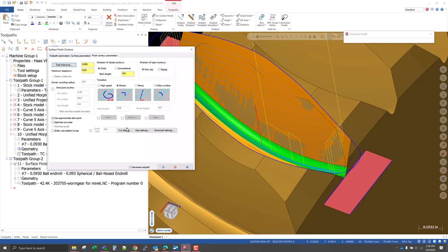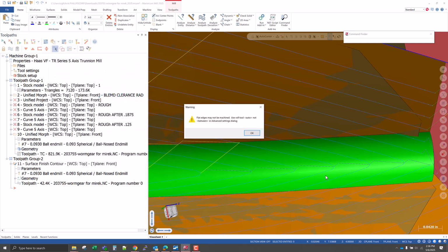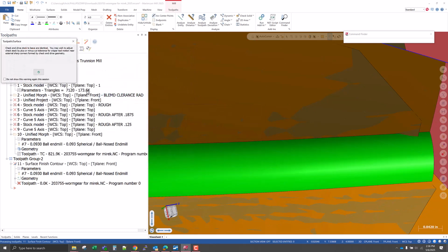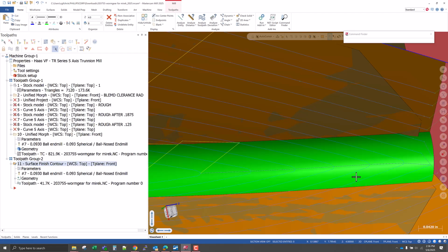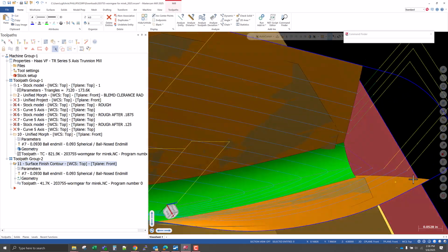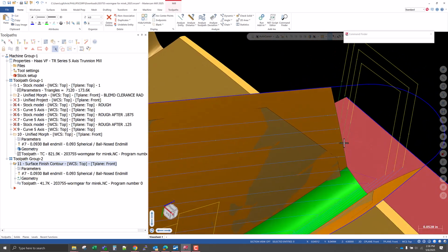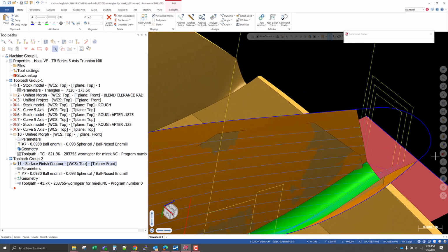So first thing we're going to do to clean up is follow surfaces. So instead of this little jagged, broken step down here, we can use follow surfaces, and we're going to get this nice, clean, smooth motion. We're still getting some jumps over here. So wouldn't it be nice if we could just connect those with this nice, smooth curve? Well, it turns out we can.